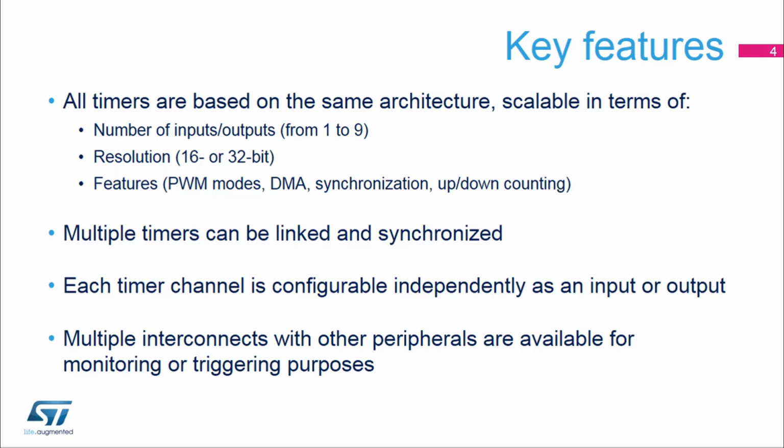Most of the timers can be linked and synchronized to build larger time-based timers, have a higher number of synchronous waveforms, or handle complex timing and waveforms. Within a timer, each and every channel can be configured independently as an input, typically for capture, or as an output, typically for a PWM. The timers can serve as a trigger for other peripherals, for instance, to start ADC conversions or to monitor the internal clocks thanks to the interconnect matrix.